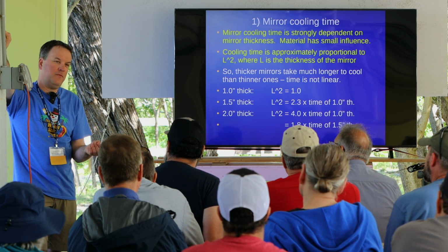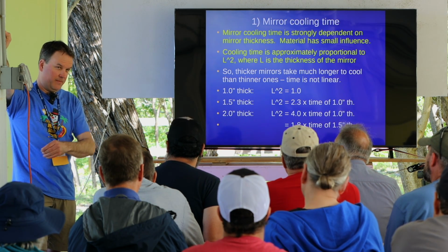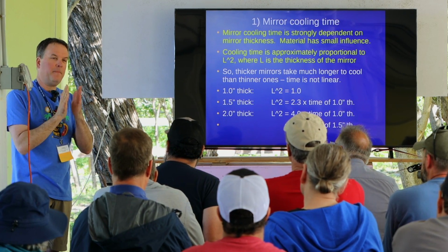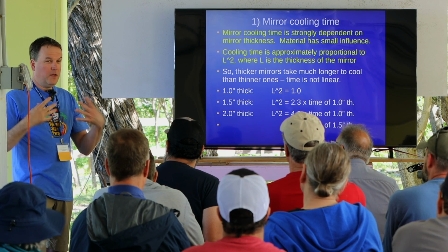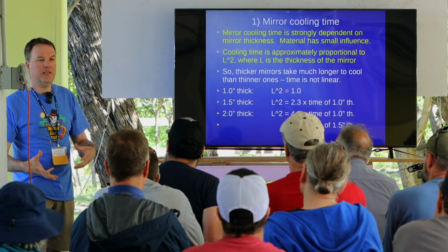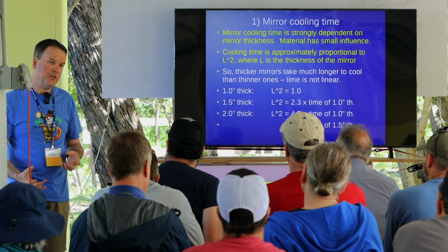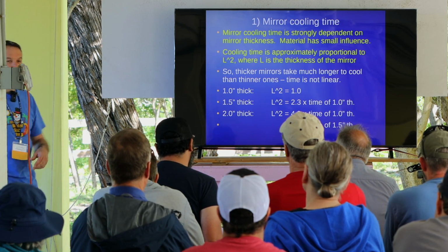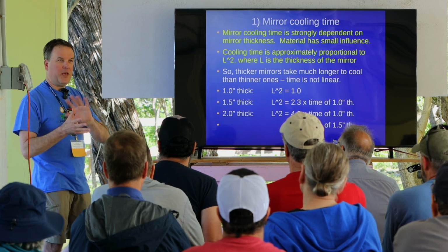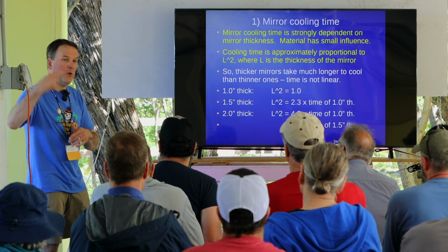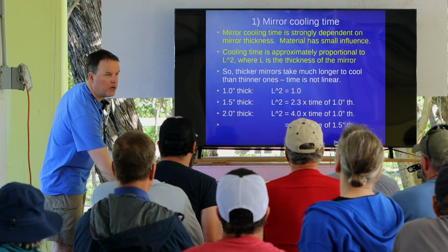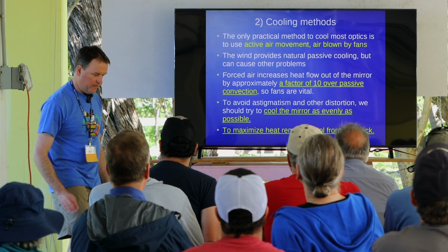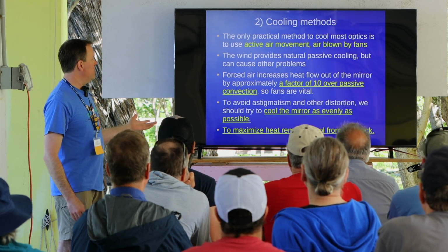For us, that'll just massively distort the mirror, generally, because you'll have something almost adhered to the back and it's metal, so you have a big temperature gradient. People have done Peltier coolers, but it's going to distort the glass. How much depends on how aggressive you are and the other conditions. It's a physics problem. You can actually calculate it out or simulate it. But generally we use air because then things behave more uniformly, and I'm going to go into this in a little bit here. So is there a talk right after me at 3? I believe so. Okay, I'm going to go as quick as I can then because I want to get to everything here.